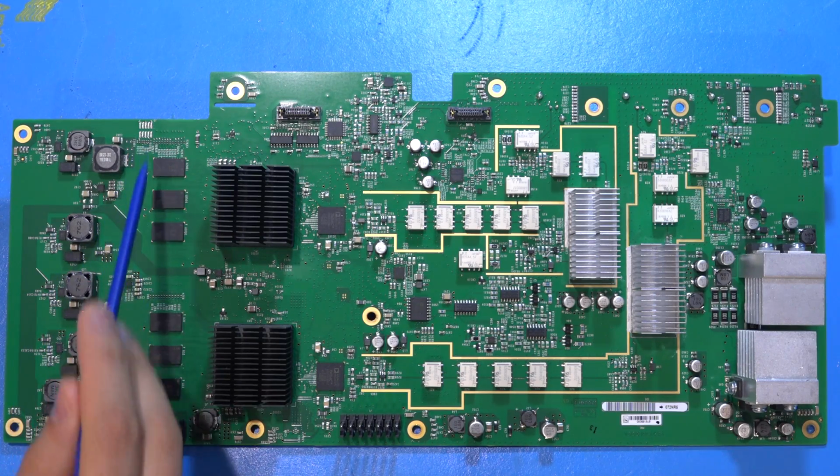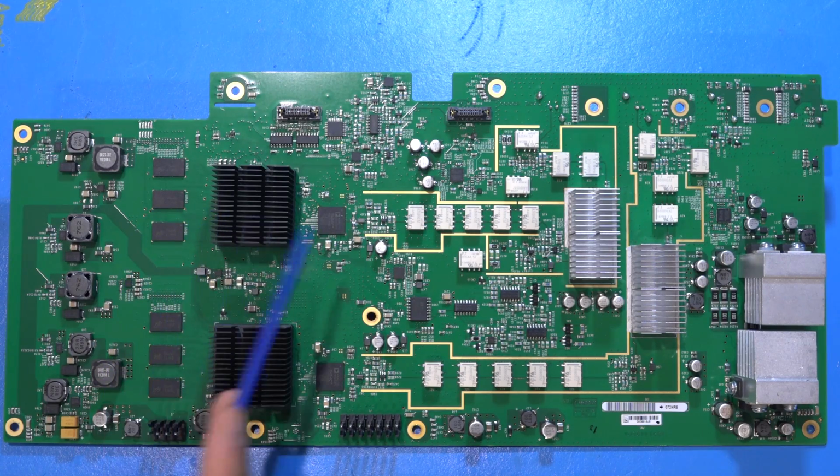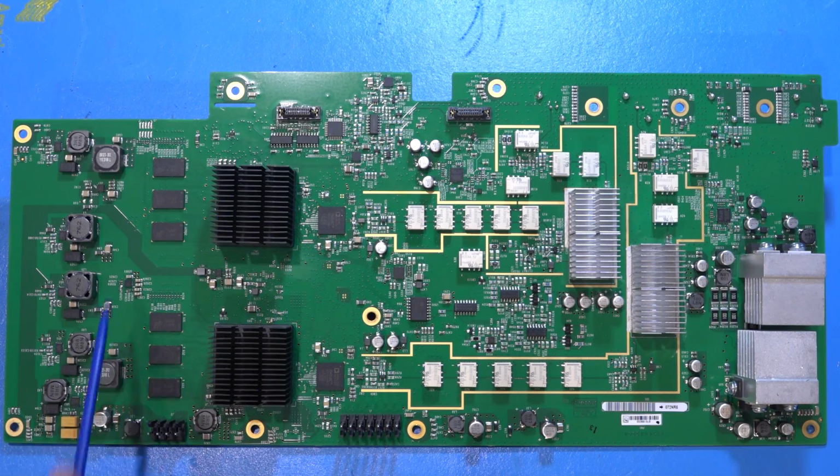And it's obviously, once you put everything in here, going to be grabbed from the memory through the FPGA and put onto the DAC at full rate. So you're not going to do anything else once everything is stored in the memory. The FPGAs themselves may potentially manipulate the data depending on what's being displayed before it's applied to the DAC. Now the interface between the FPGA and the DACs is a JESD differential LVDS type interface.